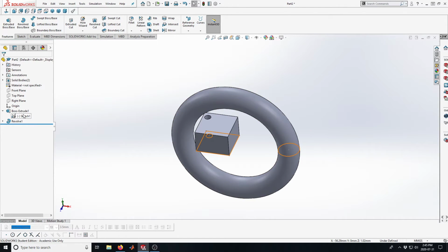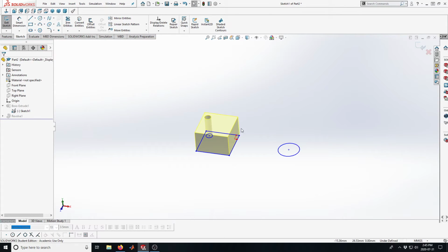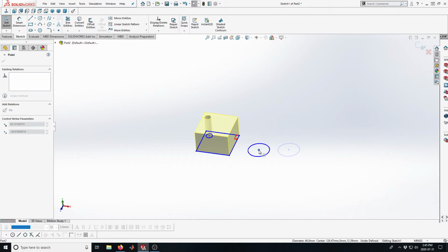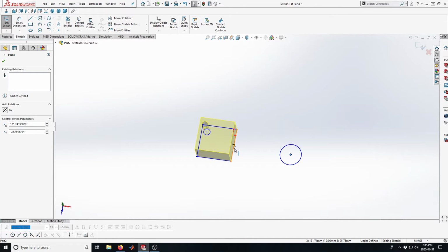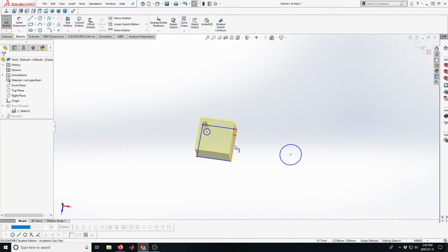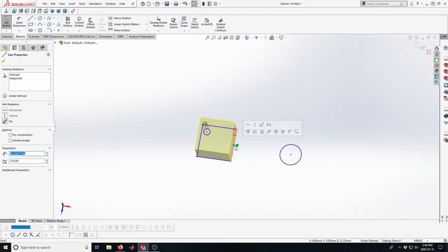Now that maybe wasn't what I wanted, and so by editing only the sketch, I can change things quite a bit. So for instance, I can start adding in the sketch some relationships. I can scroll around, and you'll notice that if you hover over a line, it selects different features of that line. This is the midpoint. I'm just going to right click that. Oops. And if I didn't want to do that, there, right click, select that. I guess I left clicked that.